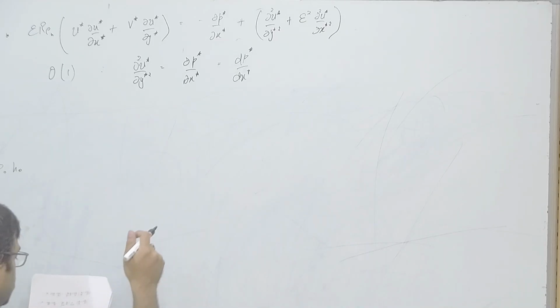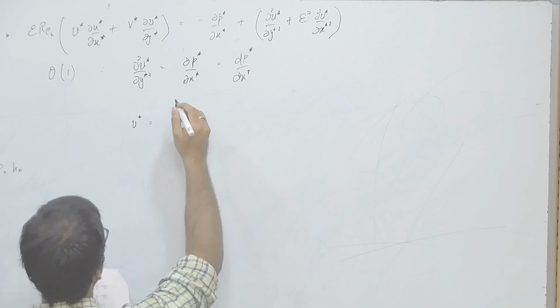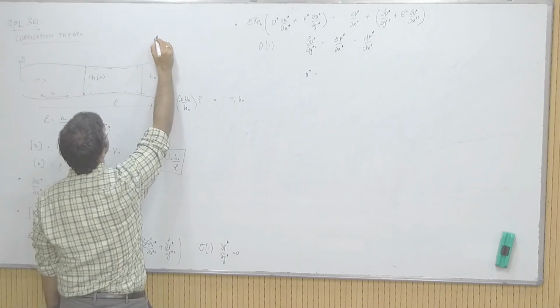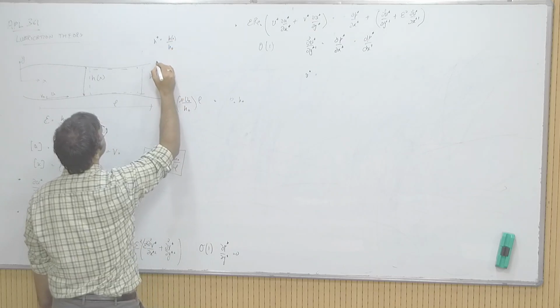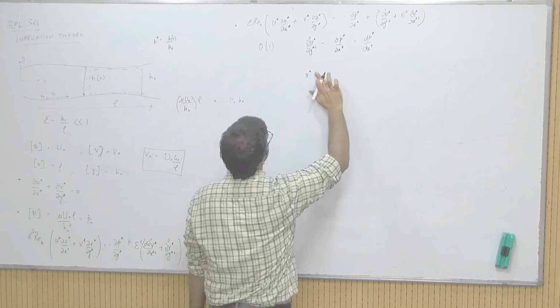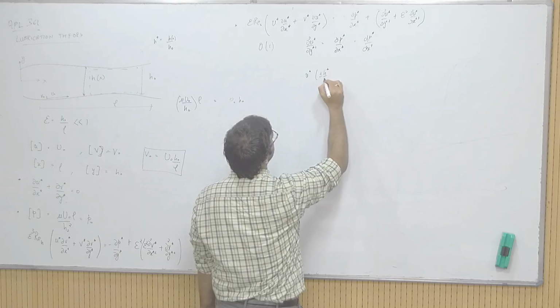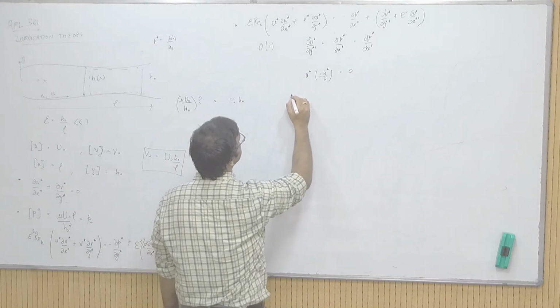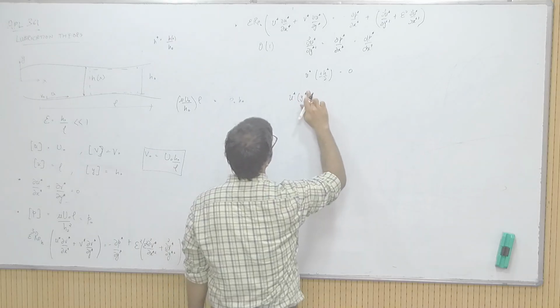the continuity equation. So if you solve this equation, you will get that u star is equal to, so the boundary conditions will be that let us say we define h star, which is h of x over h naught, and the boundary conditions are that u star at plus minus h star by 2 is 0. So once you substitute these boundary conditions, we get the solution of u star as a function of y star. There is x also.